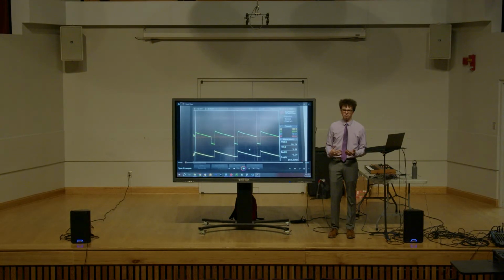An idea that I'm having that I think would fix this, I just didn't have time to get to this semester, would be to force the wave of oscillator 2 to reset to the middle of its cycle instead of to the top, and that way you're not getting a double request for the Schmidt trigger inverter to re-trigger. And that way you're just resetting the wave at a fixed point every time. That isn't going to be problematic. So you're not getting any bounce from trying to push a low voltage. You're not getting any double triggering from a higher voltage. We'll see if that works. I don't know. We'll get there.